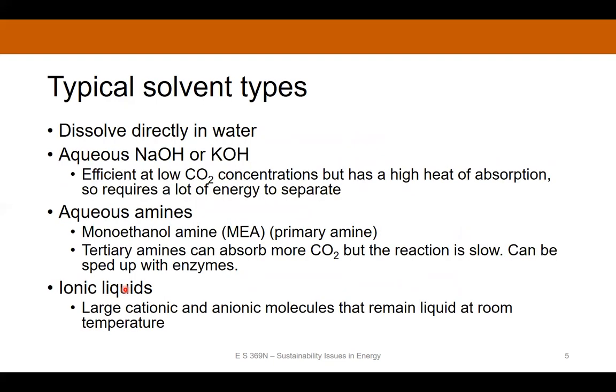So there are several different solvent types that are used in these types of systems. You can just use pure water if you're into that sort of thing, but you can improve on that. So you can also use aqueous solutions of either sodium hydroxide or potassium hydroxide. These are particularly efficient at low CO2 concentrations, and so I'll talk about these in a minute with respect to direct air capture.